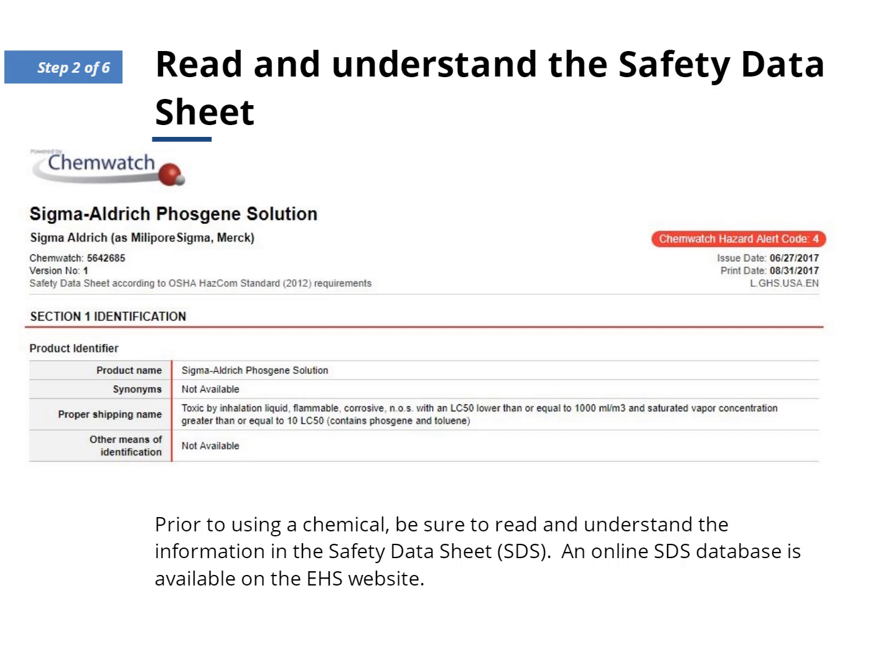Step 2. Read and understand the safety data sheet. Prior to using a chemical, be sure to read and understand the information in the Safety Data Sheet, or SDS. An online SDS database is available on the EHS website.